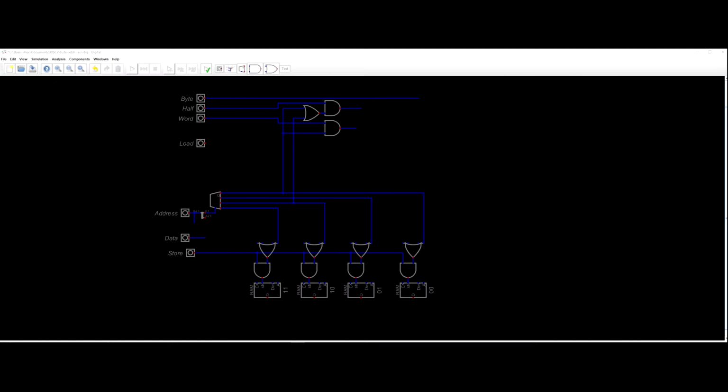So if we have a 24-bit address and you're dividing it by 4, that's like shifting it right twice. So you have 22 bits left. So these need to be 22 bits. That, or I make this 24 and then add 6 bits.